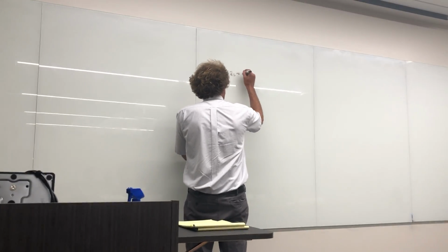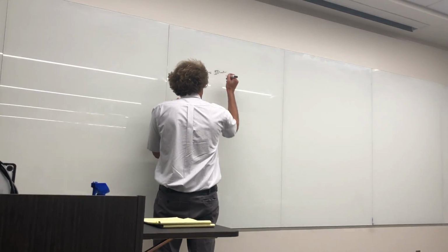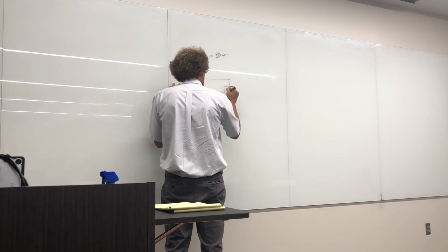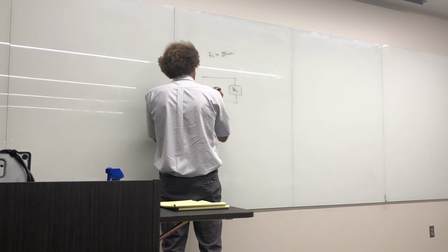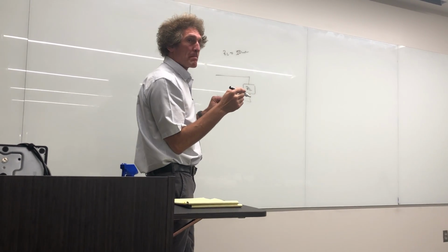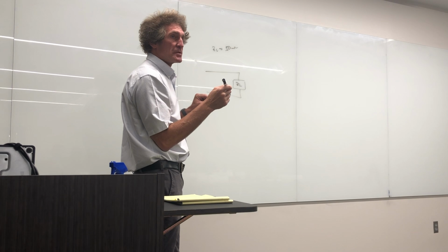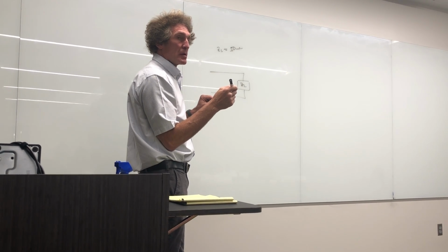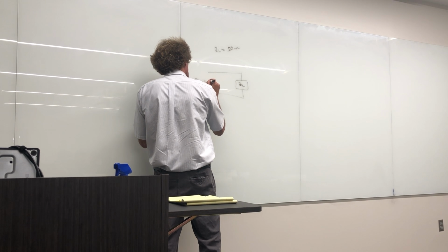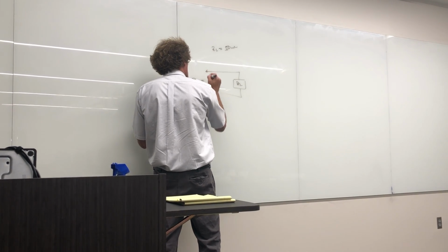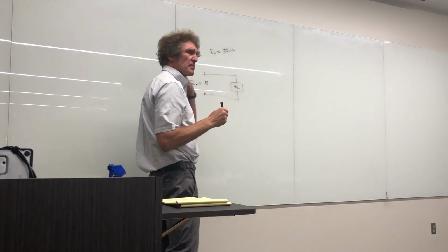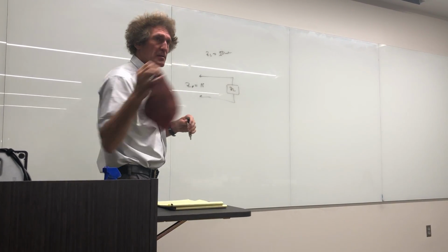Z load equals 50 ohms, okay, go ahead. And then it says, what is the reflection coefficient and the VSWR? Well, do they give a length of line at all or not? What is Z naught, the characteristic impedance? Z naught, I guess that's part of it. It's the same part. Let's see. Z naught is 18.6. No, Z in, you mean, it's 18.6. Isn't that the input impedance?